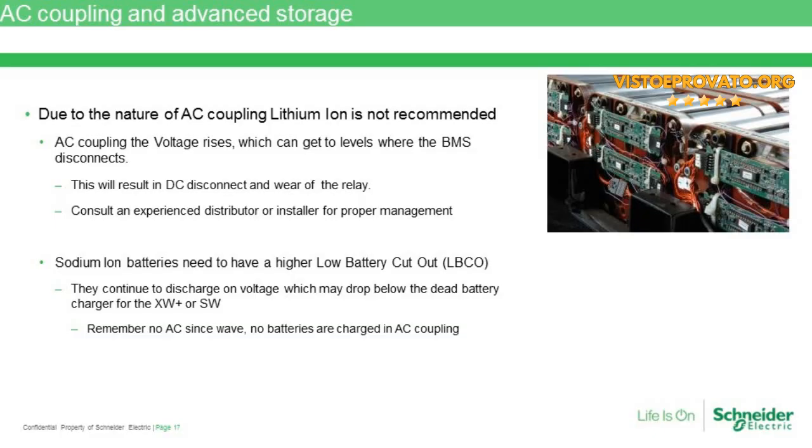So if they're only losing power a couple times a year for 24 or even 48 hours, that's only 4 cycles a year. So if we multiply that out by the life of the batteries, they're going to literally age out. The chemicals inside are going to not be available to the system because of just the natural aging process within those batteries. So definitely consider that if the size of the system says, gosh, no longer do we need to think about it as 50% depth of discharge, but 100% depth of discharge.